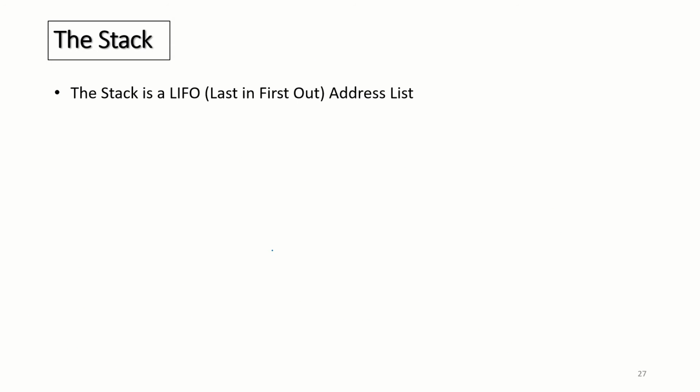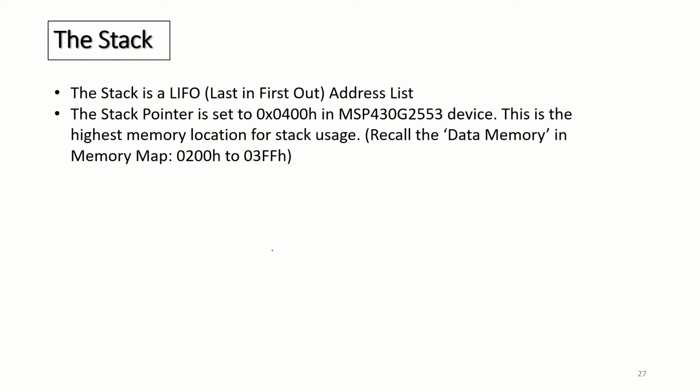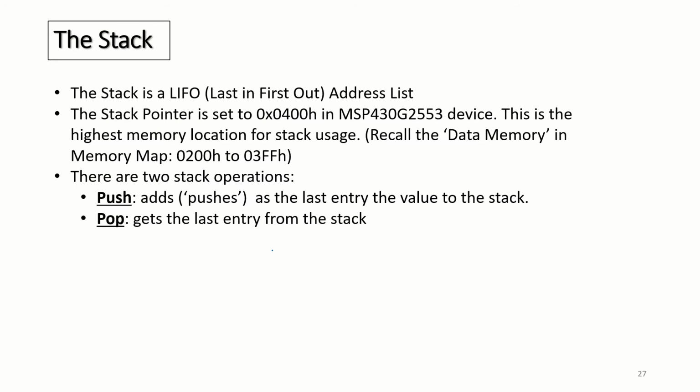Our last slide is about the stack. The stack is a LIFO, last in, first out address list. The stack pointer is set to 0400 hexadecimal in MSP430 device. This is the highest memory location for stack usage. There are two stack operations.